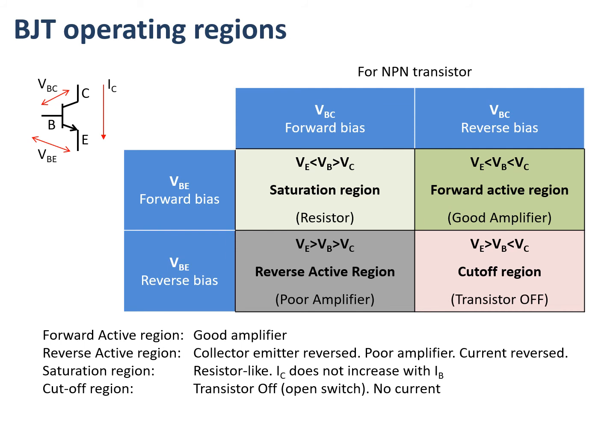There are other regions. Now in general I'm not going to operate my devices in an analog circuit in these other regions, so there are three other possibilities of the combinations here. There's a saturation region, as we've shown on the graph, where the current is rising very rapidly. It's difficult to control the current in those areas, so that's the reason why I don't use it. But I've also got a reverse situation where I've got the device effectively in a reverse bias situation for VBE, and I've also got an off region, the cutoff region, where I've got the polarities incorrect essentially, and I've got no current flowing, so I've got an open switch, if you like, in terms of that kind of way of representing it.